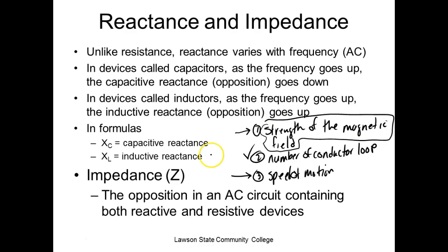So that's spinning, guys. So what we have are these things called slip rings, if y'all seen them. And they're nothing but solid copper rings. And then they got these things called brushes, which are carbon brushes that ride against the slip rings. And then this goes out here, and this is what's spinning around with it. And of course, what usually goes out on your alternator is these brushes. And you go out and buy another $200 alternator, and they send it down to Chancey's down here on 4th Avenue, and he changes the brushes out for a couple bucks.